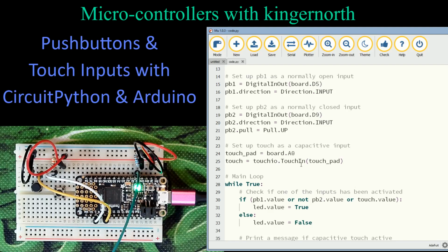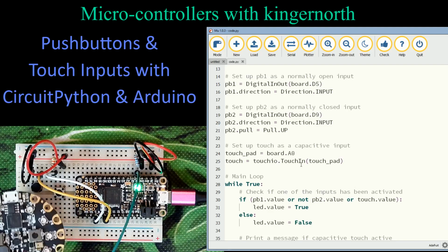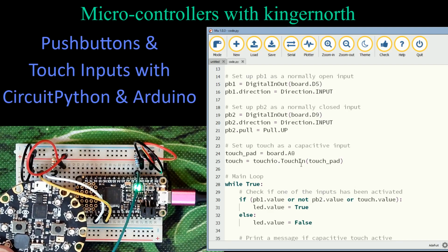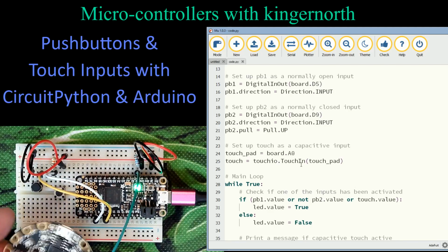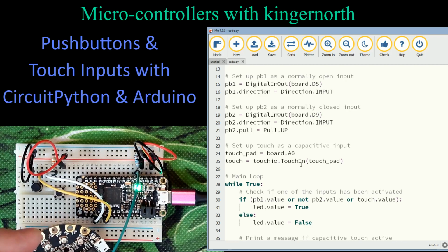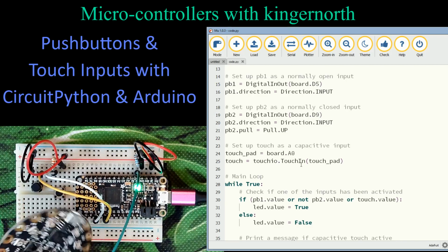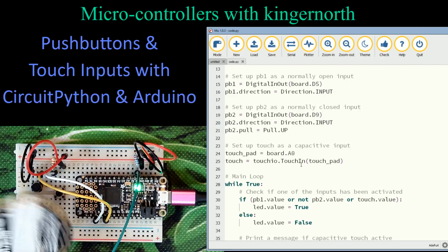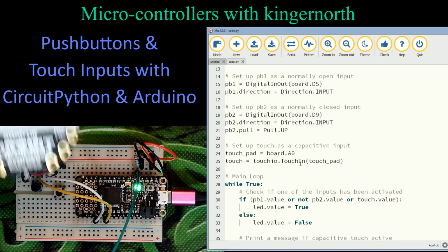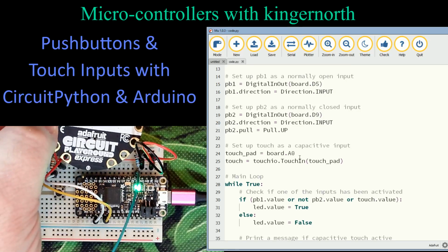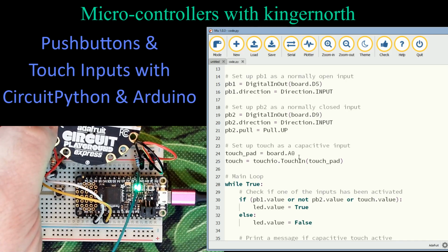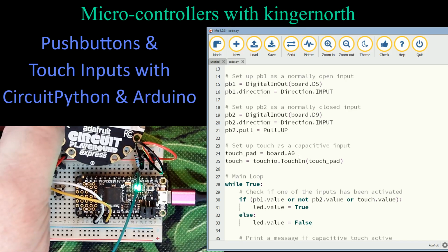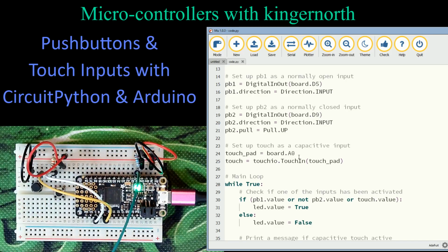Remember I said before I wanted to introduce this board at the proper time? This is the Circuit Playground Express. The majority of these input and output pads on here are also touch capacitive. The difference is that on this particular board, the Circuit Playground Express, the high megohm valued resistor is already built into this board.